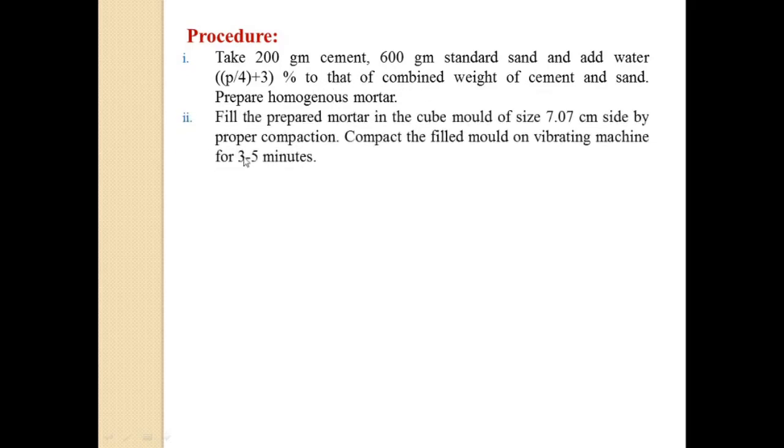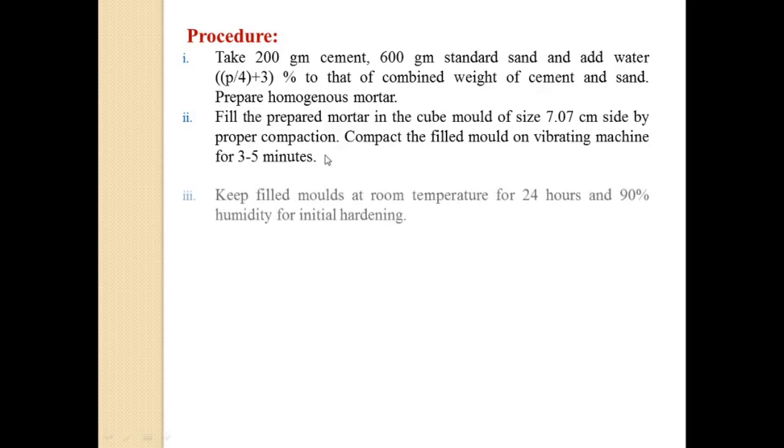Second point is to fill this prepared mortar in the mold of size 7.07 centimeter side with proper compaction. Compact the filled mold on a vibrating machine for 3 to 5 minutes. So we have to put this assembly over the vibrating machine for 3 to 5 minutes, so that we remove the air bubbles which are present in the cement mortar.